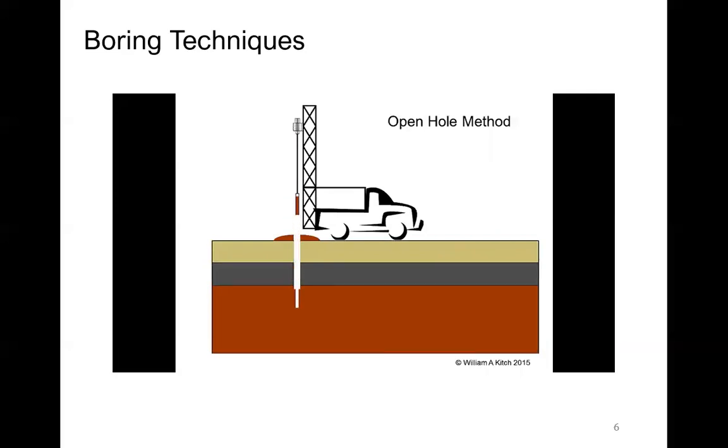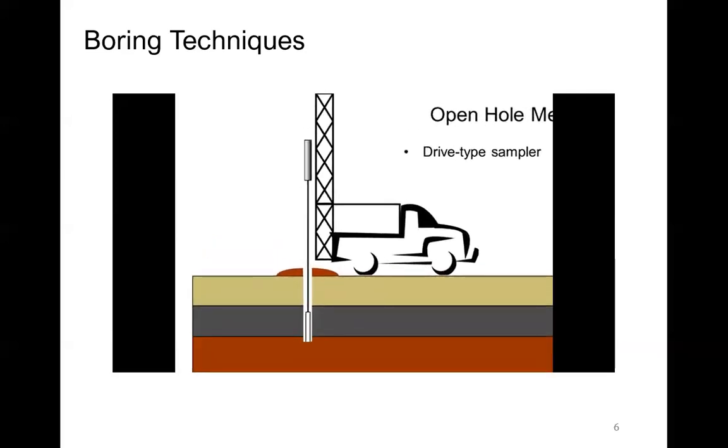It's not a big deal, but if this is 50 feet down, there's so much rod that needs to be pulled up before they can replace it with the sampler. In these circumstances, we use a heavy wall sampler that can be driven into the soil using a drop hammer. The process is similar to retrieving a push type sampler, but uses different equipment and a different sampler.